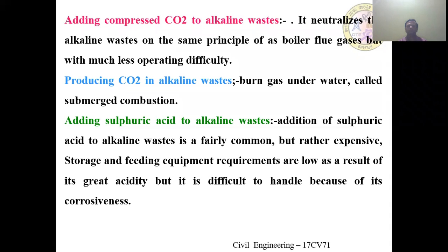Adding this carbon dioxide to alkaline waste neutralizes the alkali waste, with the same principle as boiler flue gas but much less operating difficulty. That is, here we directly pass CO2 gas. How are we going to produce CO2 in alkaline waste? By burning gas underwater, called a submerged combustion condition.